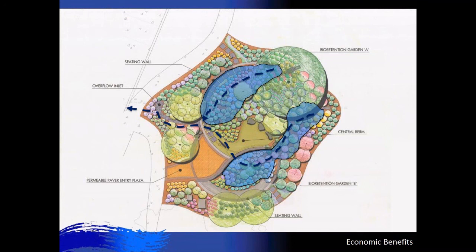So we utilized it for a side-by-side comparison of 2 alternative bioretention prototypes. One of the underdrains was lower with an elbow, and the other one wasn't as low, and we were just trying to allow for future educational opportunities to really explore this as an outdoor classroom.